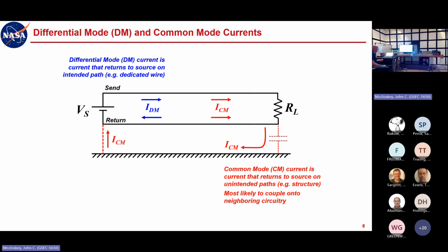When you're making high frequency common mode measurements, you have to pay attention to the fact that you're dealing with a mismatched transmission line, and that current distribution is going to be a function of the position of the probe. If you know that you're dealing with a shorted termination, then put the current probe near the short. But in this case, for whatever reason, I just thought I was dealing with the same kind of configuration, and I clearly wasn't.